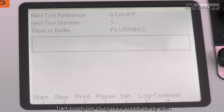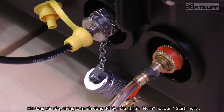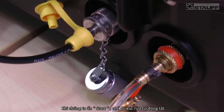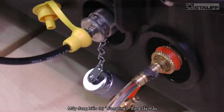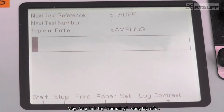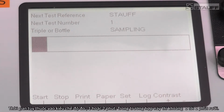So now we've flushed the particle counter, we can press the flush button to turn it off, or we can immediately press start. When you press start, valve automatically closes. So now the machine shows us sampling, and the progress bar also indicates the progress of the sampling. This process usually takes about a minute or two, depending on the type of test, but in this case it's about 1 minute or 1.5 minutes.